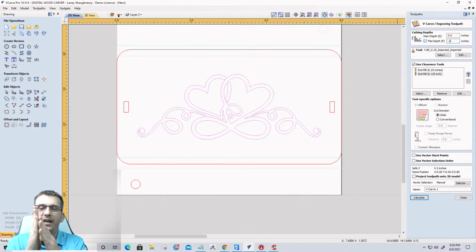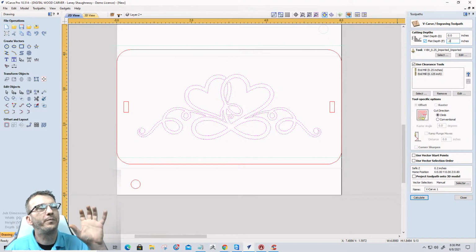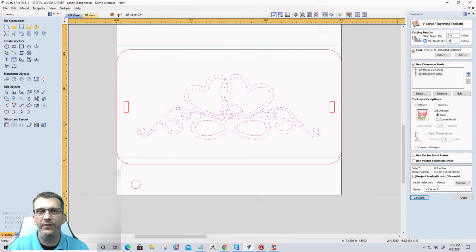It's not really going to be a cut. It's more going to be kind of ripping through the wood, but where it won't fit into my inlay, right? Especially when I'm cutting the male part and all. So 0.2 is my maximum cut for the particular bit that I'm using. I use a 60-degree 0.25 V-bit. You can do a 90-degree V-bit, you can do a 30, you can do whatever size V-bit you want. Just I stress that make sure that the flat depth, your pocket depth basically, does not exceed the cutter length.